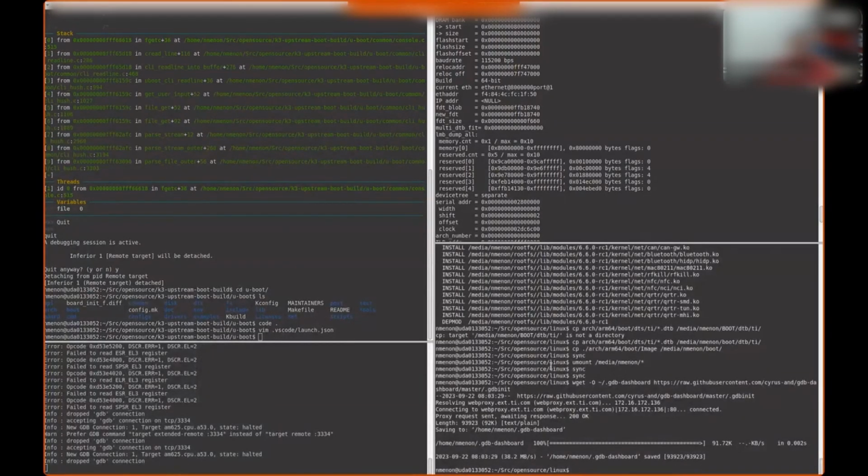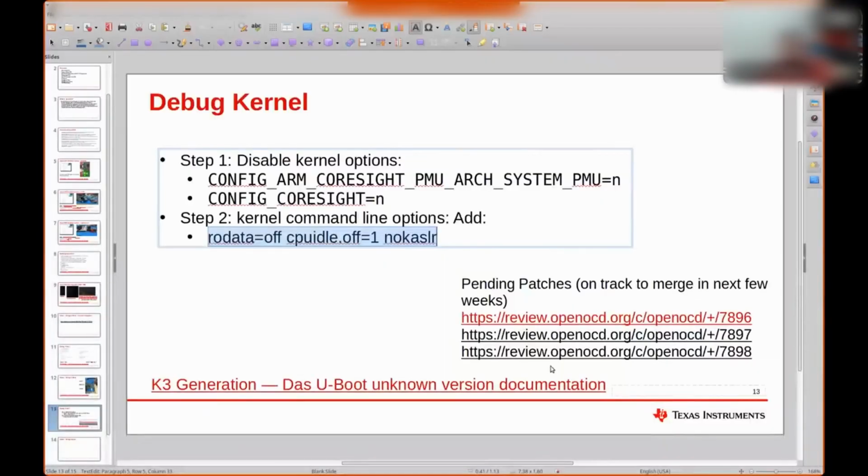So Sean, do you mind if I interrupt you for a second? Sure. The other one that I've run into is perf events. I've disabled perf events because the kernel will use hardware breakpoints for those, and it will wipe them all out. And so yeah, go ahead. Yeah, so the PMU perf is the option that I had to disable within the default defconfig. I didn't have to completely disable perf either.